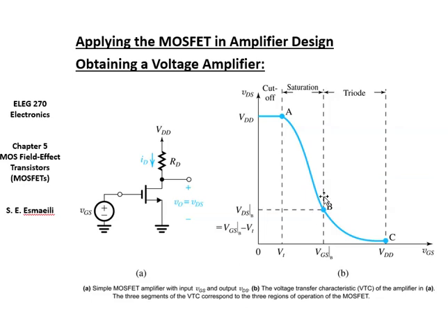It means a change in the gate source voltage can result in a bigger change in drain source voltage. So it can be a voltage controlled voltage source, right? In the BJT, it could work for us as a current source, right? So here we can kind of have a voltage amplifier. So we're going to continue to see how to analyze it in AC.